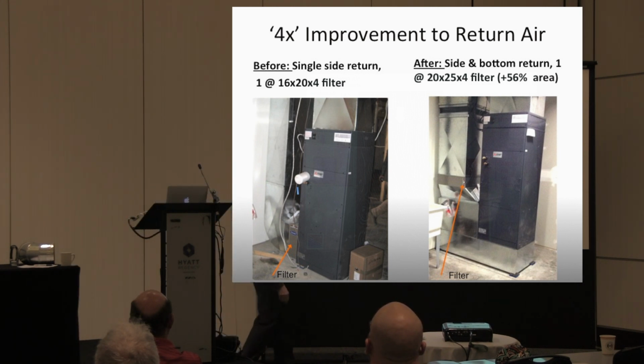This, by the way, is what I'm representing right now, which is the cold air return of most basement houses. Air comes down from the ceiling, makes this corner, and this outlined area is what I'm presenting here. The furnace fan here is actually oriented the other way with the inlet here, and this is the hot air delivery, and this is the connection. This has three problems associated with it.